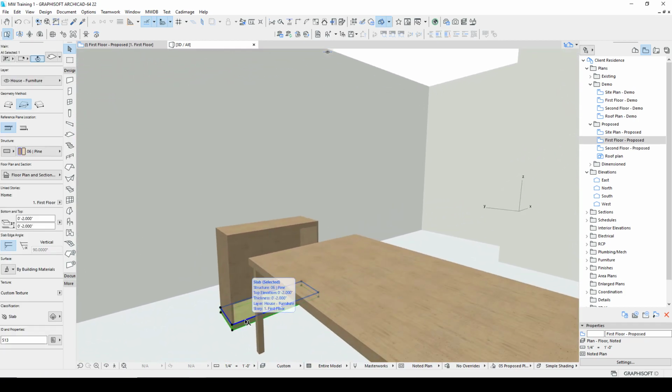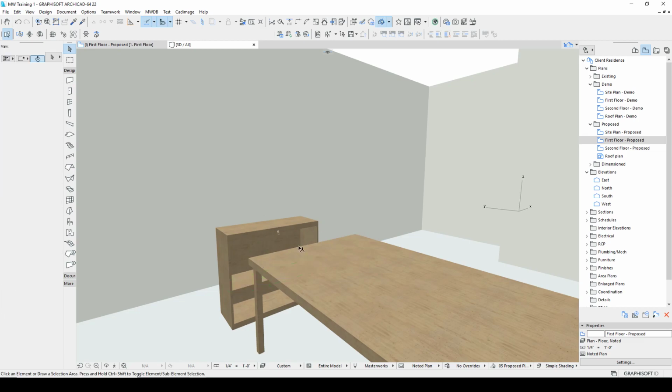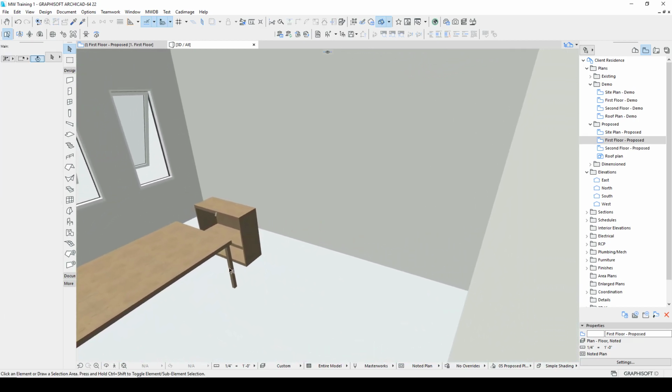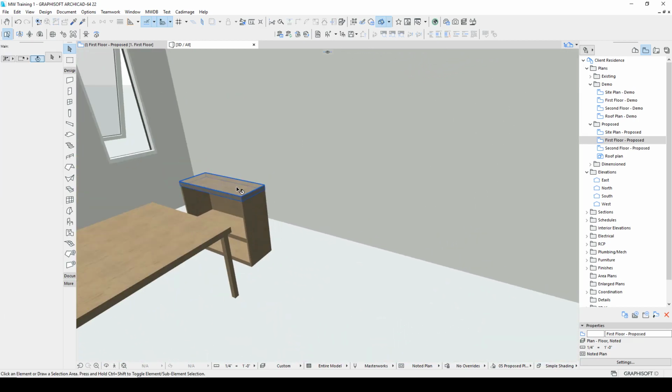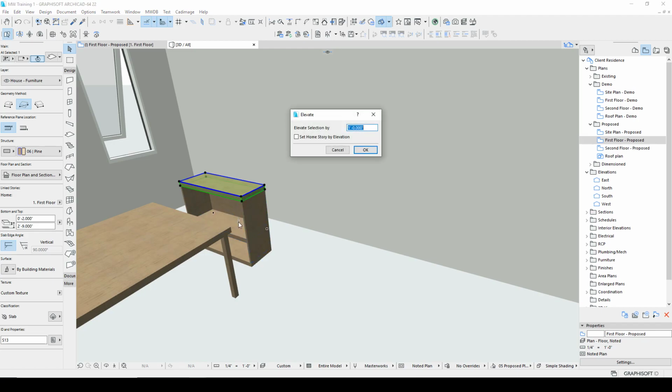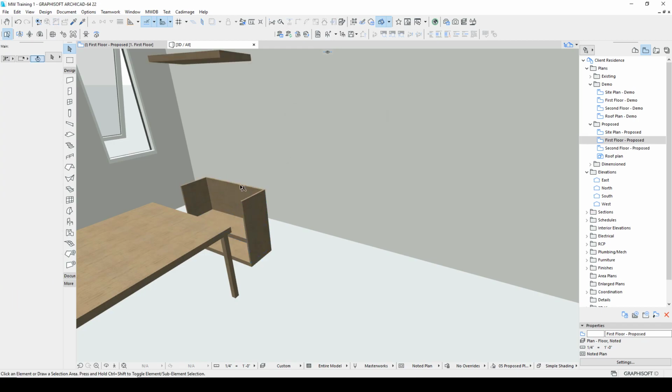If I wanted to make that a shelf, I could F9 that and just click in place, and then F12 and move a shelf up. And I can move the shelf in on the 3 sides. So the shelf is actually inside the carcass. And I've made myself a little bookshelf, and it's easy to make this, you know, significantly taller.